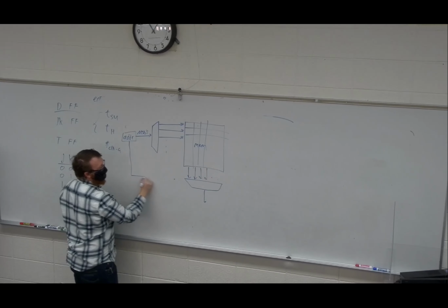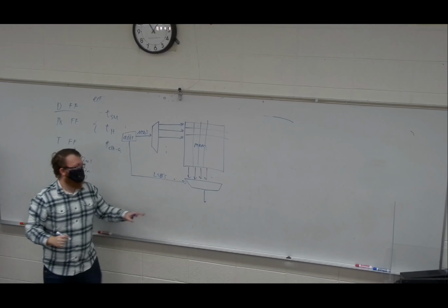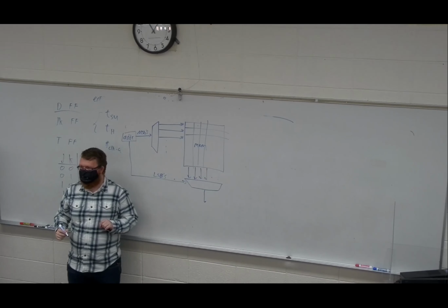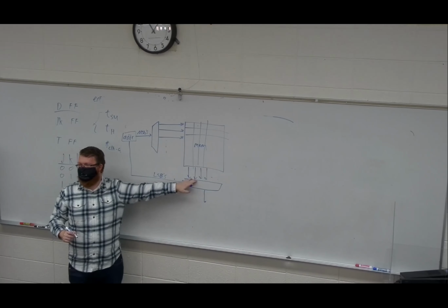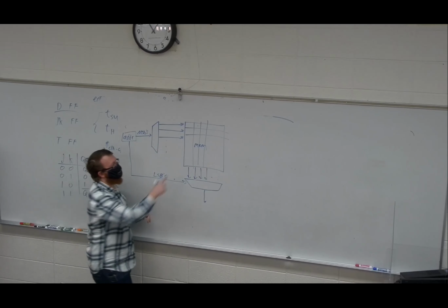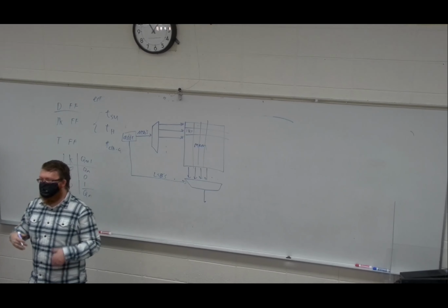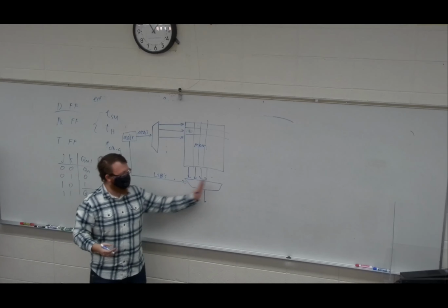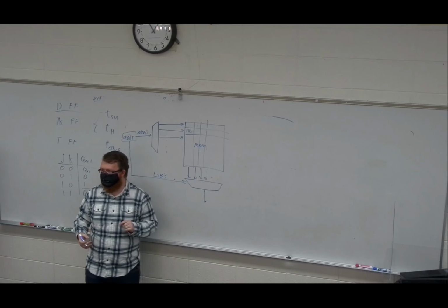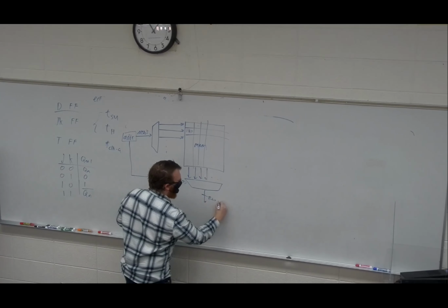And this address register will send its least significant bits to this column decoder. So we say, which row do we activate and which column do I take? And I could take multiple columns, right? Especially if you think of each of these as one bit. I'm going to have a word length, which is how long this is. How many do I take out at one time? So this might be an 8-bit word.